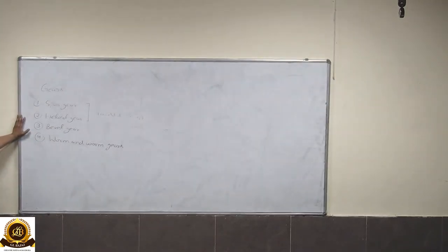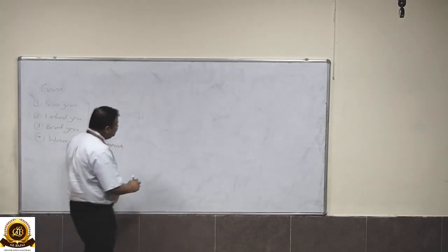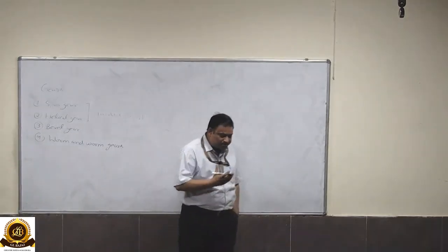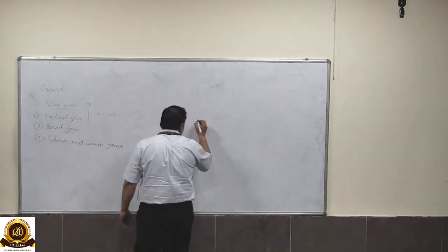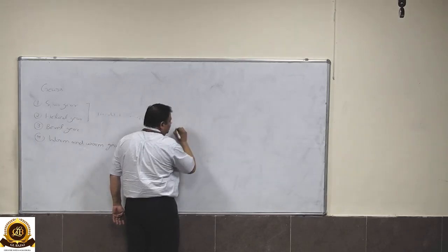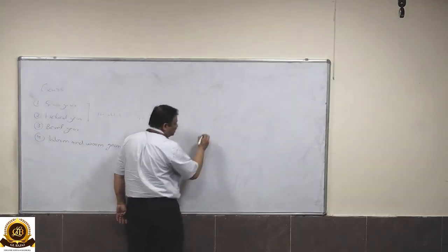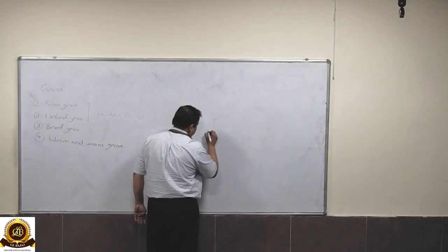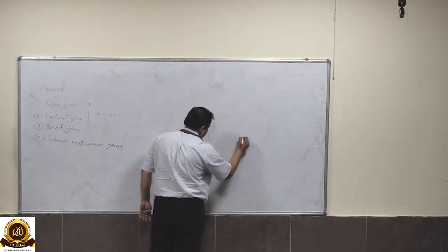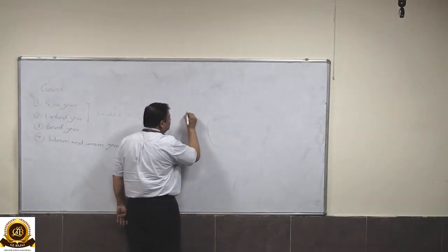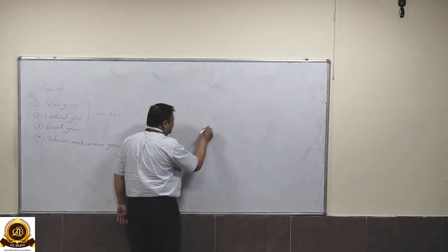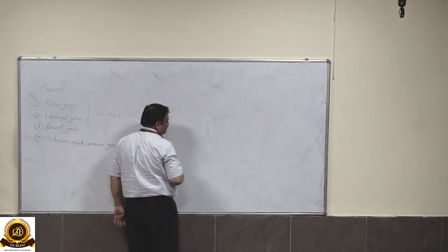Now, the exact velocity ratio is basically used to get a constant angular rotation of the wheels. Consider two friction wheels to transmit the power, one smaller and the second larger.